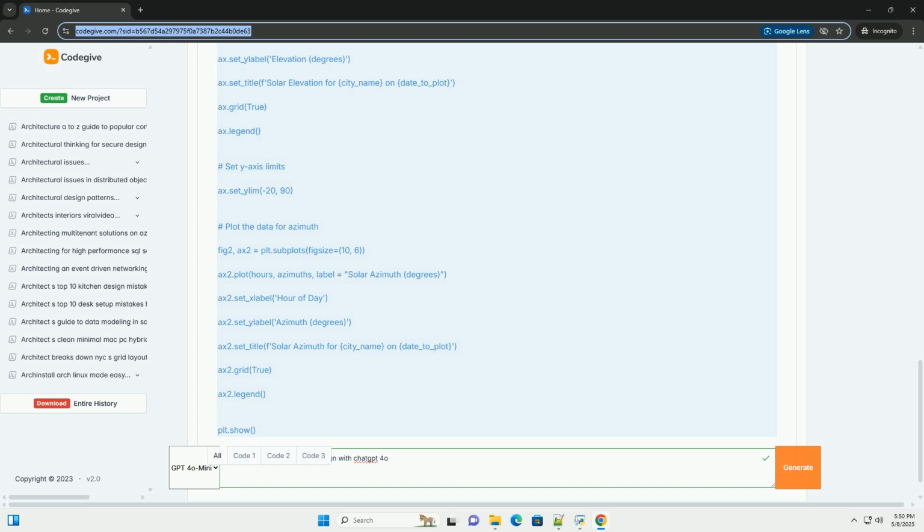2. Dynamic fenestration pattern: instead of uniformly spaced rectangular windows, create a dynamic fenestration pattern. Use windows of varying sizes and shapes, arranged in an asymmetrical manner. Incorporate a ribbon window that spans the length of the building on the 2nd floor, providing expansive views. Consider using tinted or fritted glass to reduce glare and heat gain while adding visual interest.